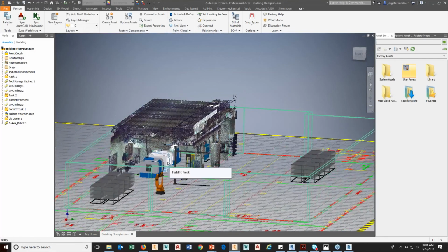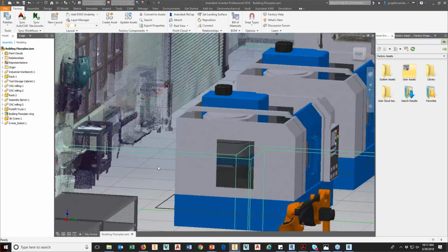So we can start to see some of that capability here, being able to empower ourselves to make sure that we're designing this the way we expect it to be designed. And if you use something like Navisworks, you can do clash detection as well and make sure that you're not running into the different areas, and it'll actually highlight them in red. So this gives me a nice little reference point just to fact check myself, if you will.